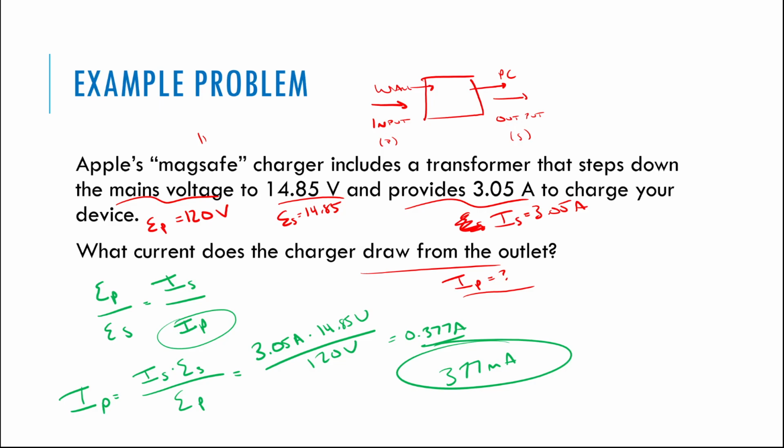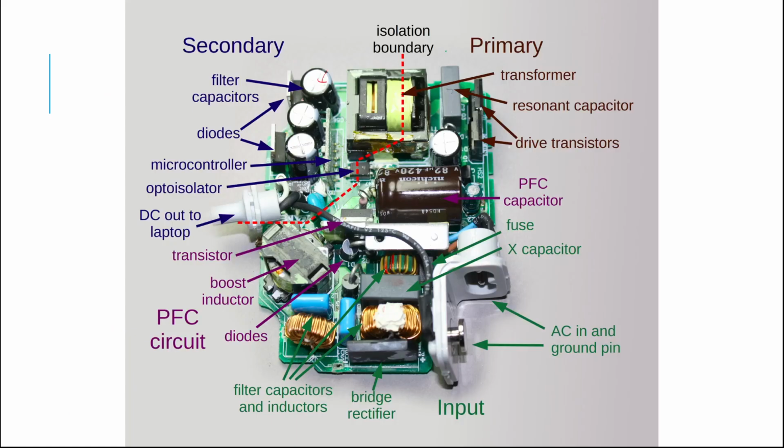That's the equation that tells you everything. But the big concept, again, is we're using these different numbers of coils of wire to step up or step down the voltage. So we can change the voltage and current proportions as needed, minimize heat loss when we transmit power, and get a nice amount of current so we can charge stuff and do stuff with electricity at home. So there you go. There are transformers for you to start using now in your practice and lab stuff and beyond. Have fun.